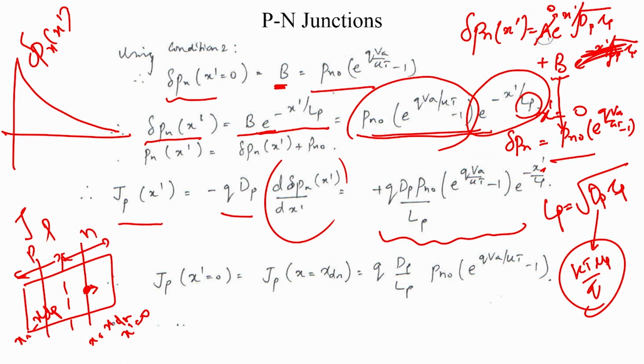because after this point it becomes a little tricky to compute the total current, because you have a diffusion component and you have the minority carriers moving in, etc., etc. So, we want to compute the diffusion current at this edge due to the holes, we want to compute the diffusion current at this edge due to the electrons, and sum these two diffusion current components to give you the total current. So, at x dash equal to 0, my diffusion current simply becomes this particular term.